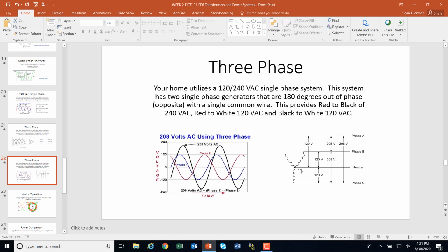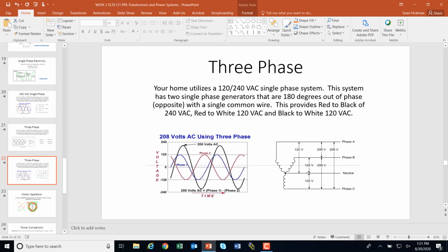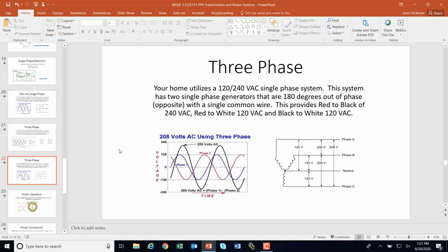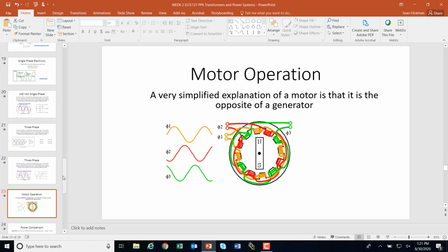And we have the neutral wire, that's a 0. Then we can get A to neutral, B to neutral, and C to neutral, and those are my 120s. Okay, so once again, I will clean this up there, but that's the 3-phase.